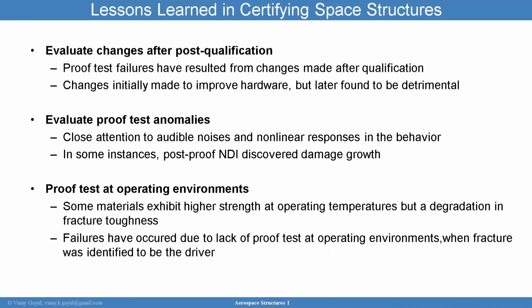You want to pay attention closely to audible noises and nonlinear responses in the behavior, because you're going to have strain gauges during the proof test. And you may feel very tempted to say, I don't think these are issues. But in some instances, post proof NDI discovered damage growth. And so it's very important to understand that NDI is going to provide a lot of value.